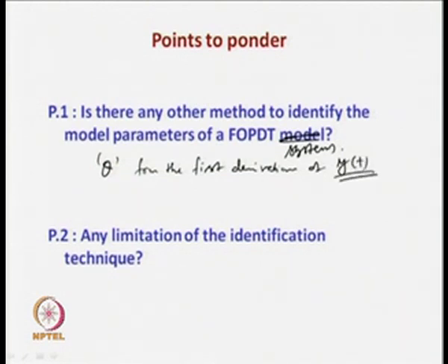When there is a large change or a discontinuity in the output, then the time taken to that point from any zero crossing can be taken as the time delay associated with the dynamics of that system. Then the remaining 2 parameters k and T1 can be estimated using any 2 expressions we have derived earlier.